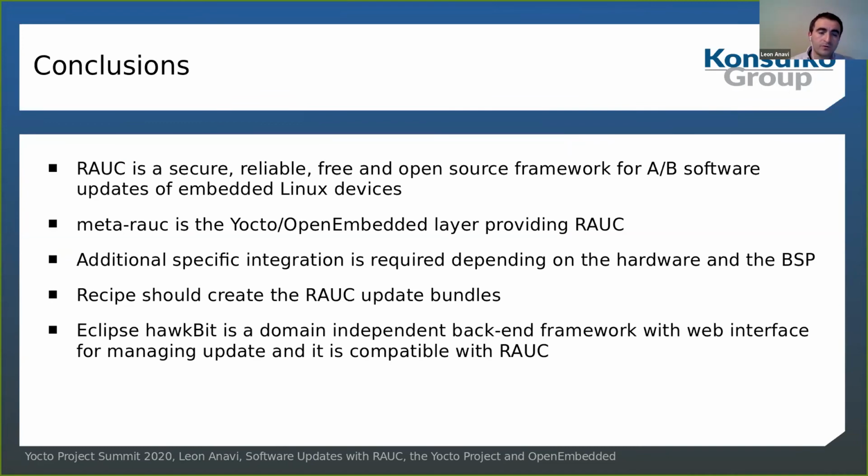RAUC provides the tools to generate bundles for the update, which are part of the whole integration for Yocto through the meta-rauc layer. It also provides the rauc tool in the command line on the embedded device to perform the actual update.